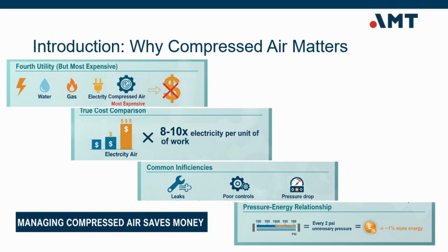There's also a simple but powerful relationship between pressure and energy. For every 2 psi, or pounds per square inch, of unnecessary pressure, energy consumption increases by roughly 1%. That means small pressure increases quietly add cost every hour this system runs. And most compressed air systems run continuously.